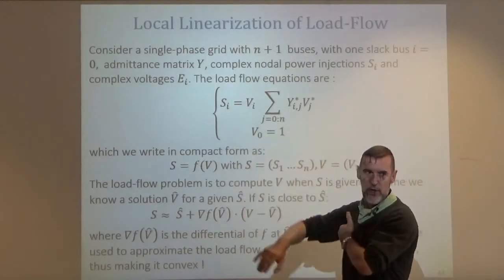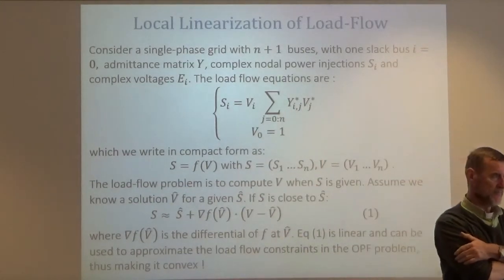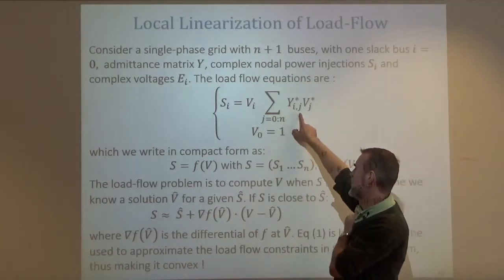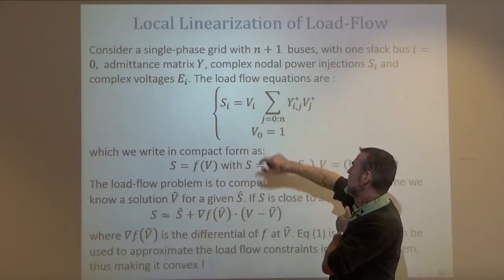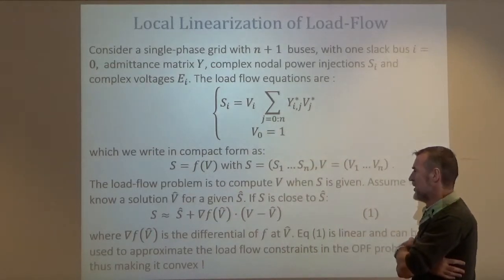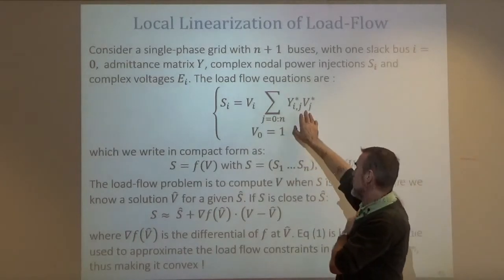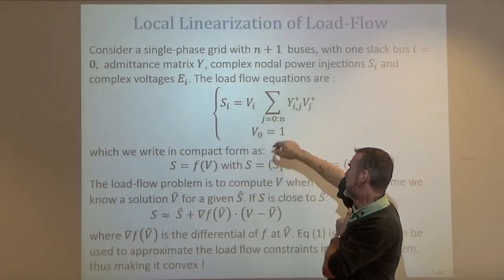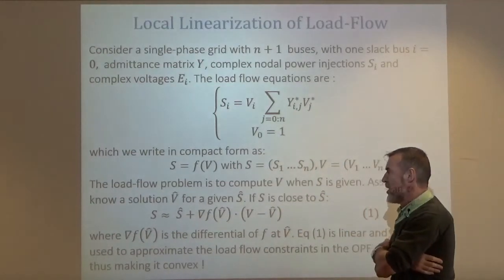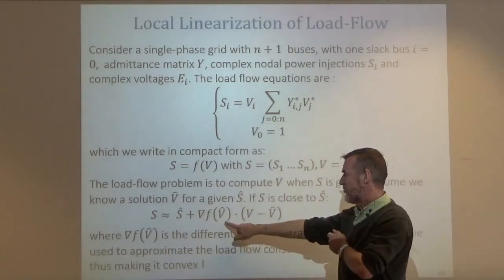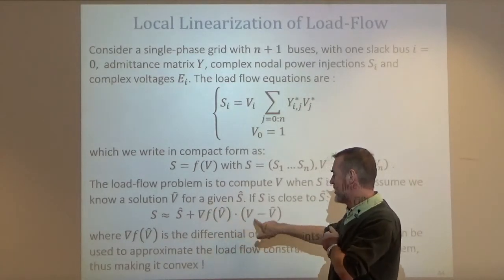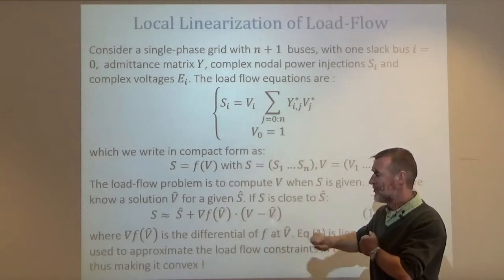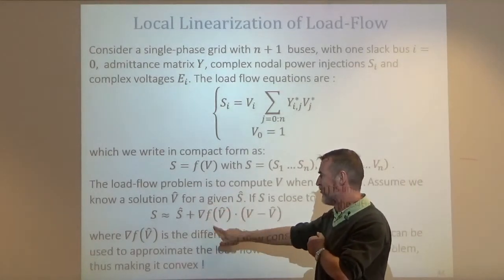Those are the fundamental equations of the admittance matrix, which are true also if there are shunt elements. So in the general case, the shunt elements appear in the diagonal terms. And this is nonlinear. It's quadratic, in fact. If we take the rectangular coordinates, there will be quadratic components in the V's. But I can do a linear approximation by taking, if I am at an operating point, V hat, the matrix of all derivatives.